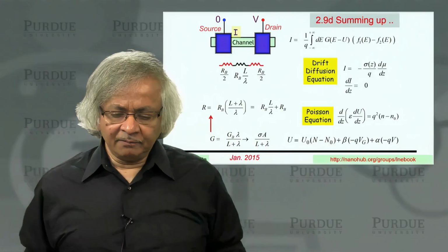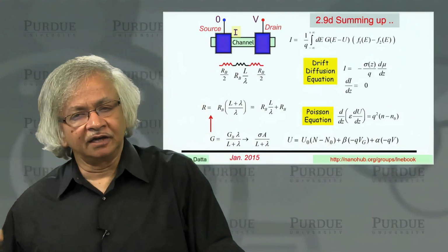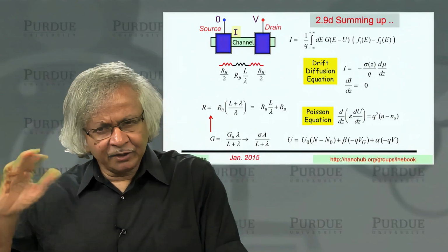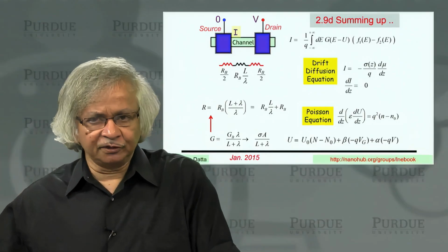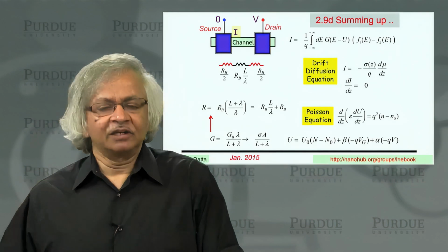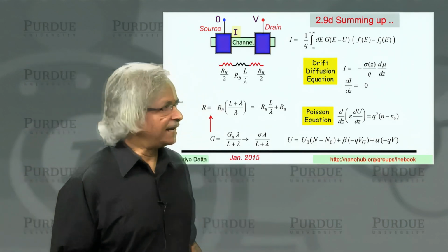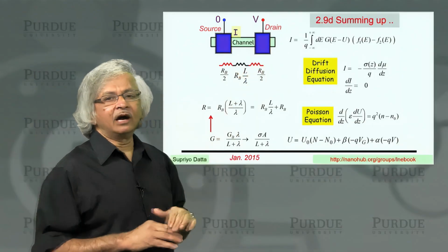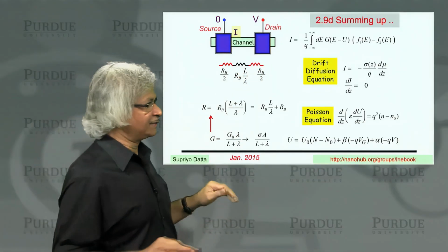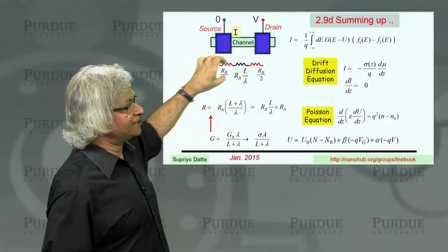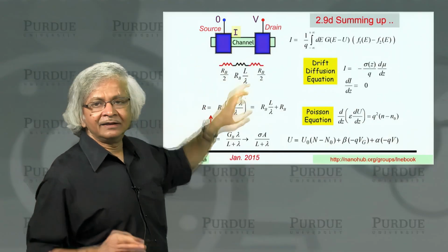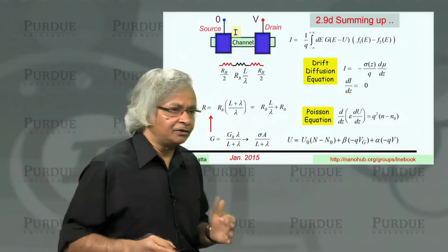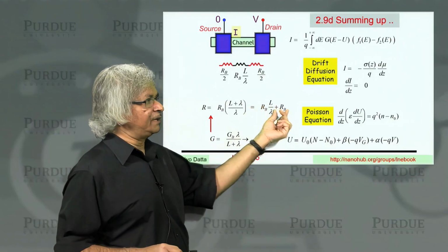That's well known. But usually you think of this contact resistance as an undesired thing, which you can always get rid of with enough engineering. What is not recognized is that there is actually a fundamental limit: no matter how good your contacting technology is, finally you will always have this ballistic resistance appearing at the interfaces. Now this is something we haven't talked about so far. You see, we didn't quite talk about where this RB comes from.